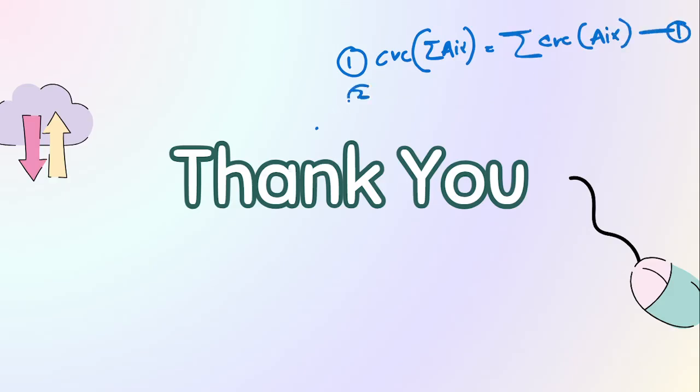The second was that, if you think of a word of CRC, right? If the CRC of something like a byte followed by x to the power k, right? If there are k bits of zeros following, then you basically take the CRC of the byte and then evolve it. So we took a table of that CRC, right? And we evolved it by pushing in n or k bytes of zeros. So this is the other thing that we did special.